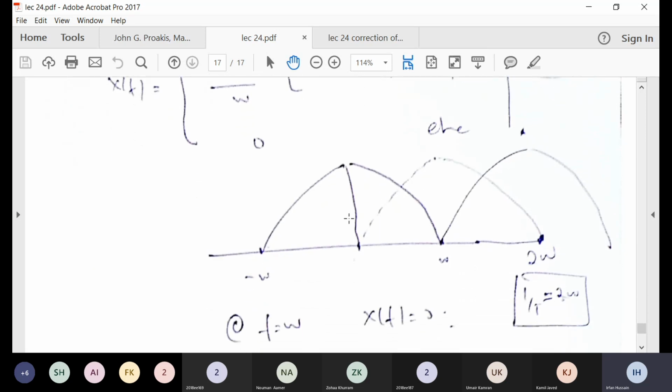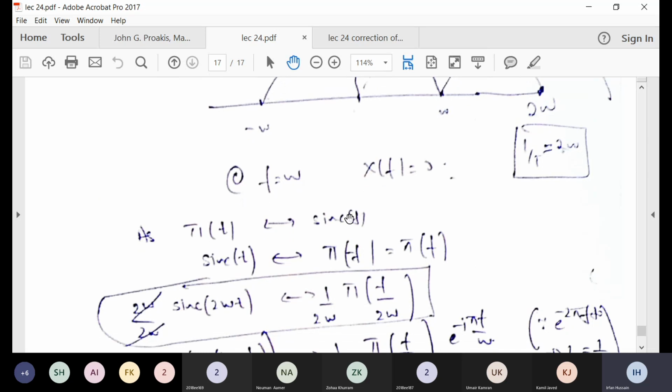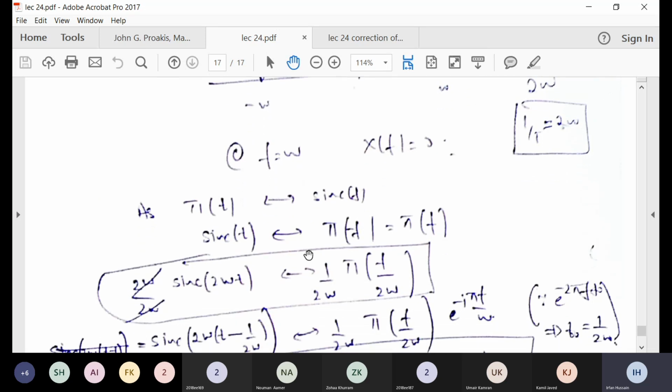We have the frequency domain cosines, and this is how we can find the inverse Fourier of this thing. So you can see, rect is sinc, or you can say that sinc is rect, but you can see that my rect is of width 2w. Sinc with this scaling by 2w means that your rect is scaled by 1 over 2w, and amplitude is multiplied by 2w.